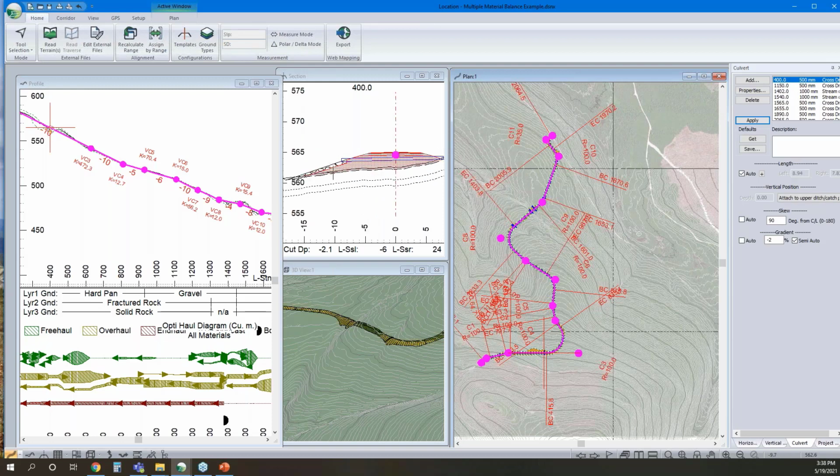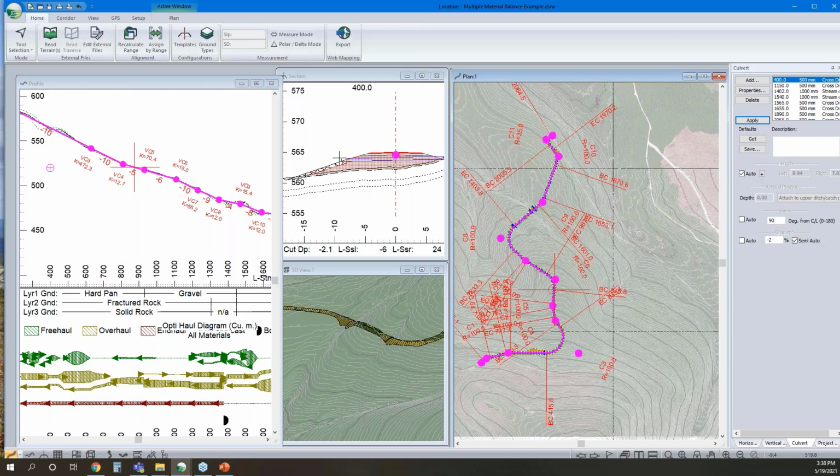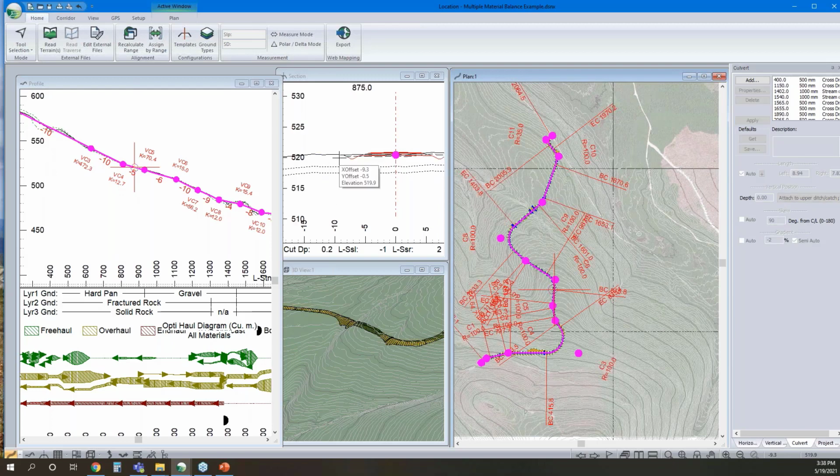Here we can see we've got a different template with the spill apron applied, versus anywhere else. And you can build your templates to include logic in them. Things like whether you have a ditch or not: it'll know if you're in fill, and it's not going to have a ditch. So they're pretty smart. And I just answered that next question there.